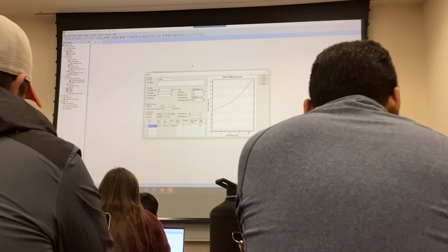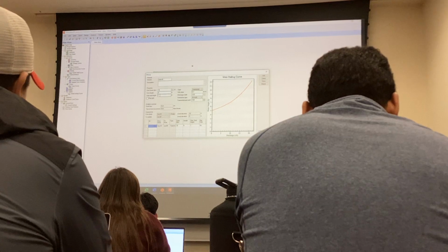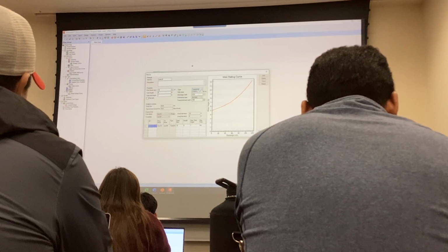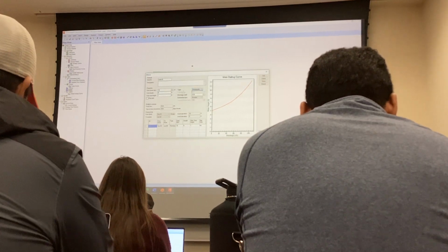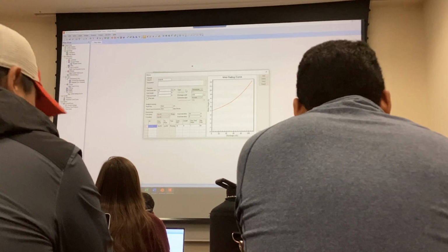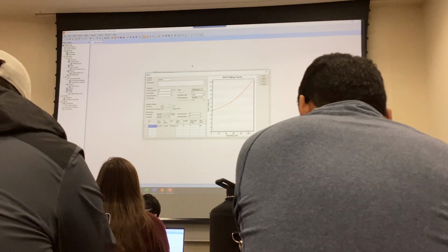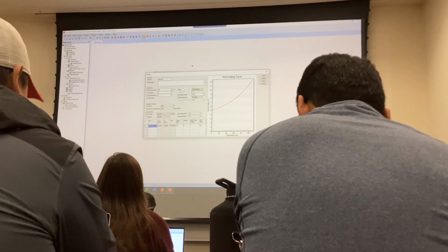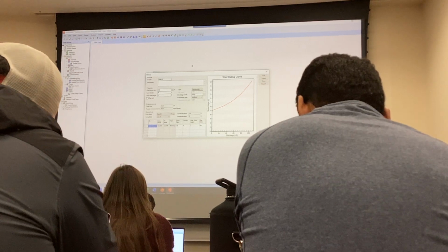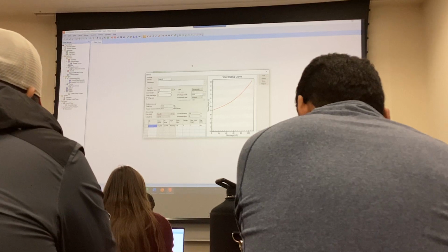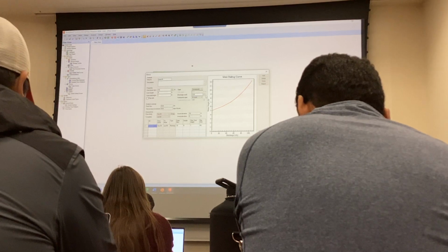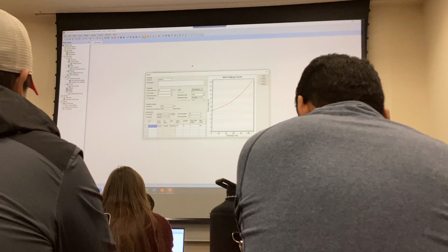And the total weir height 1 feet. Okay, this is going to be a rectangular weir. You don't need to worry about the CD being different than what we have, because the calculation is being done within, and they use a different equation. Okay, so once you are okay with that, just hit OK.